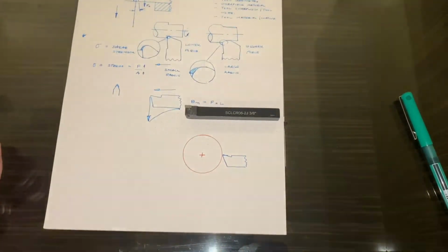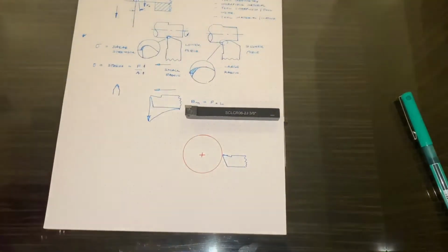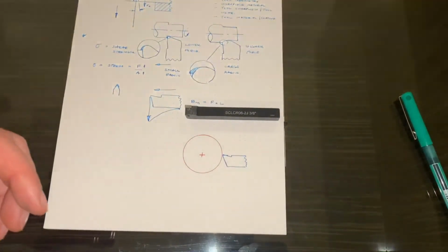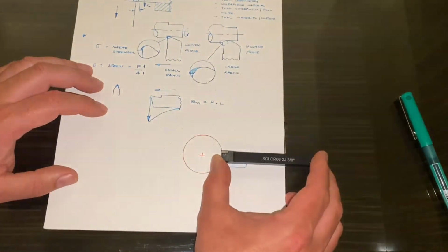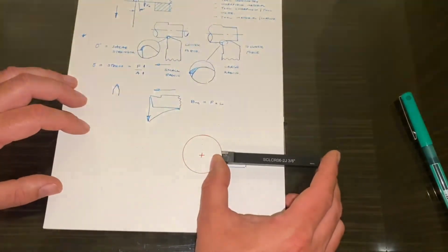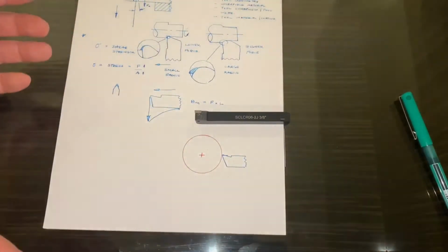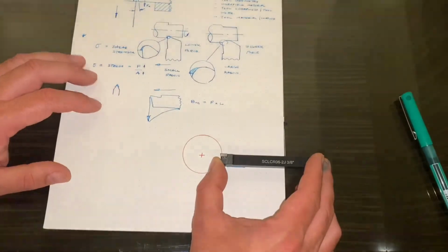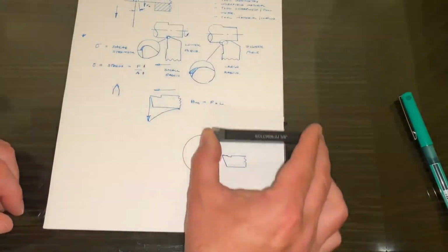One way to do this is to have a roughing tool, because for roughing, you could standardise with a standard depth of cut for certain materials, and that would be one approach. Because the forces are going to be higher, you might choose to set the tool slightly above centre height, because when it undergoes those high forces, it then drops down and compensates. For a finishing tool, you might have a different tool assigned for that purpose, more closely aligned to centre height, because the forces are going to be lower, therefore the deflection is going to be lower, and there's less to compensate by.